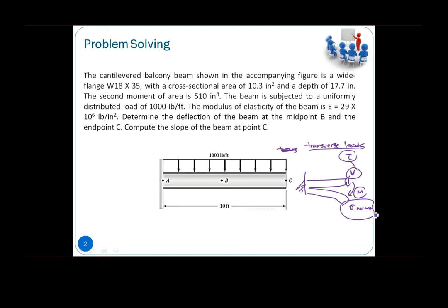So in what we have discussed under the Euler-Bernoulli beam principle, we assume that the deformations subject to these transverse loadings have no shear. If you're looking into each section, this section itself, there is no shear deformation about its plane itself. So meaning to that, if you're looking into these two planes itself, it won't be doing a shearing effect.